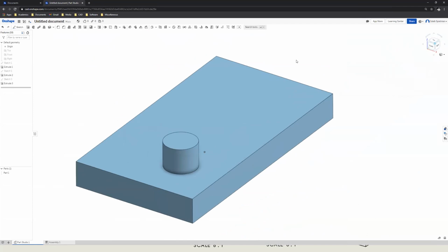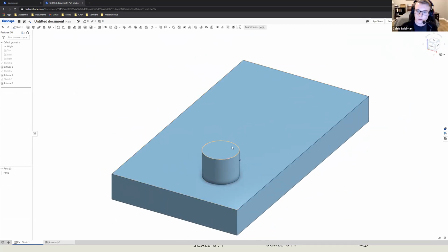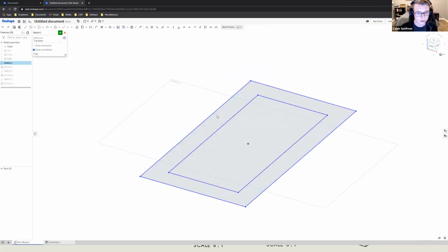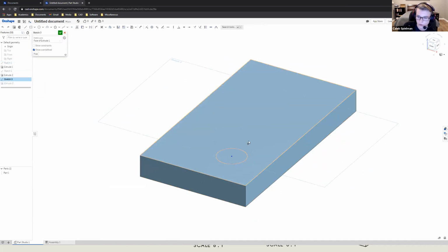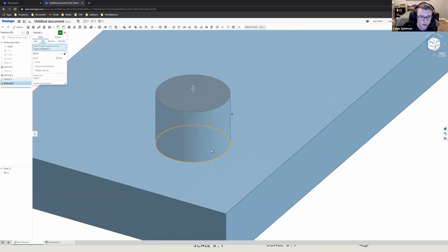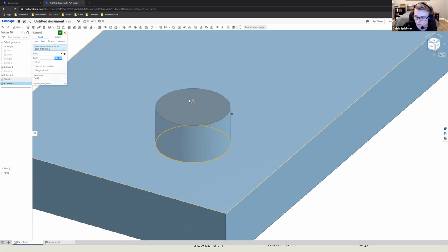Wait a second. How did you put a lid on this? All right, so let's go back to sketch 1 first. So here in sketch 1, we had 2 regions that can be defined by the sketch. We have the inside one and the outside one. And we just wanted the outside one. So that's all we selected. Here in sketch 3, we only have a single contour, and I selected that contour. So it extruded this entire contour some distance. Does that make sense? I think so.